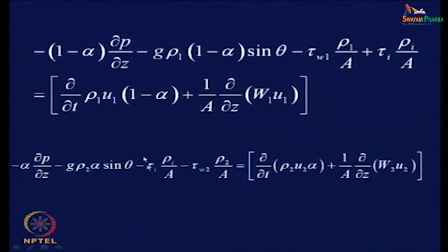Say some particular fraction of it, say eta fraction of the liquid phase, is getting converted to the gas phase. So, W1 into eta is the amount which is getting converted, and this particular amount is changing its velocity from that of the liquid phase to the gas phase, or in other words it is changing its velocity from u2 to u1. So, this mass flow rate into the change in velocity gives you the rate of change of momentum. We have to take that into account, and accordingly these expressions are going to change under that condition.